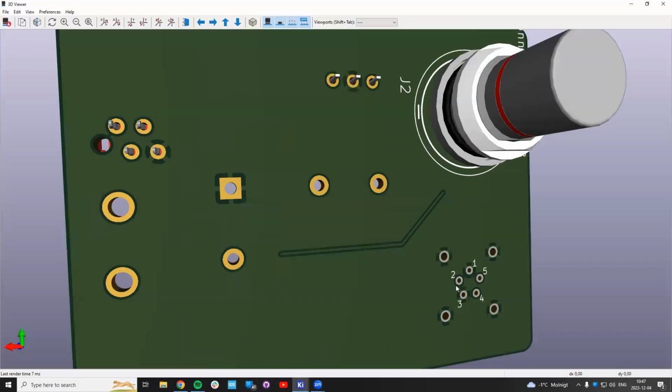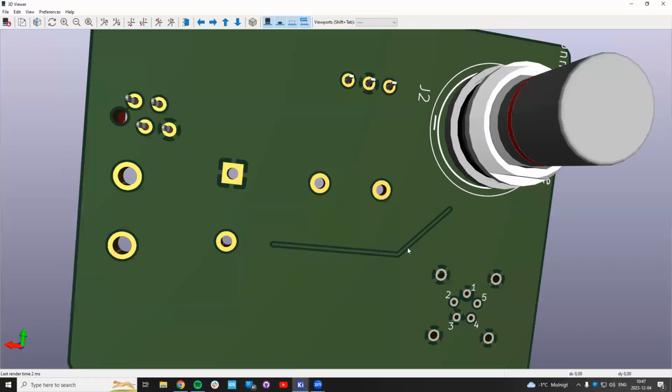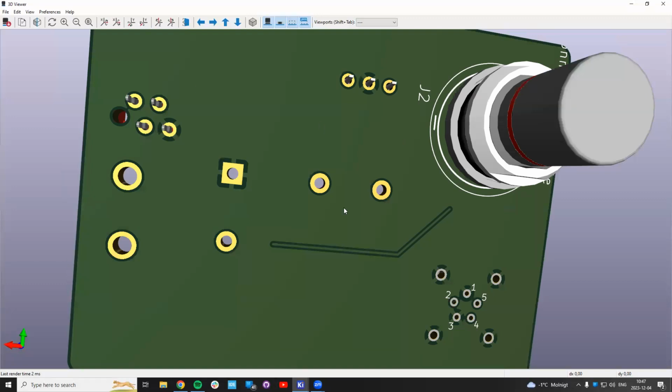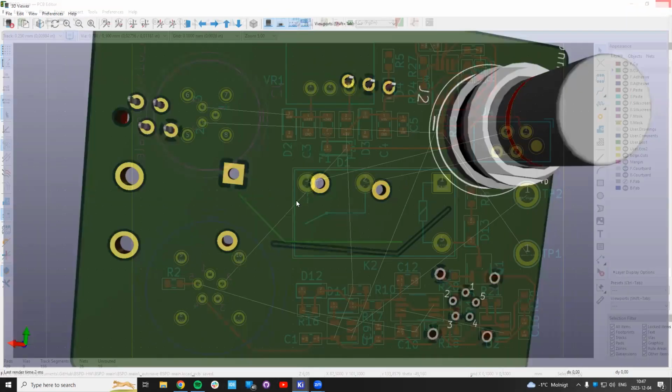The trace here, you can see, this is copper, this is some kind of net, and it's surrounded by this dark green area. That means the current can't go through here, right? So you'll have to go around. Every time the current has to go around, you're creating ground loops. This is bad for signal integrity. It also increases the loops, right? That's kind of like an inductor. It increases impedance, it increases resistance. So try to avoid the routing on the backside.